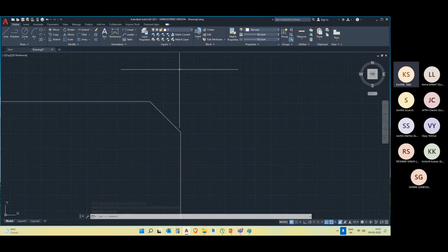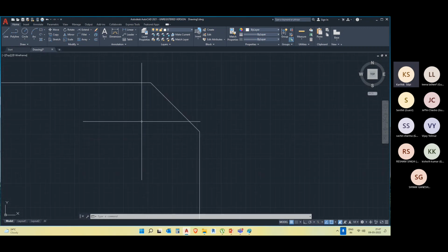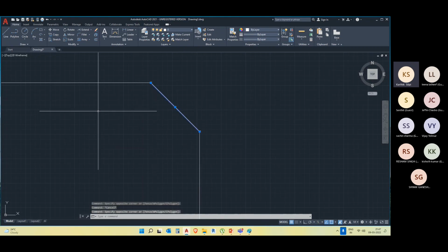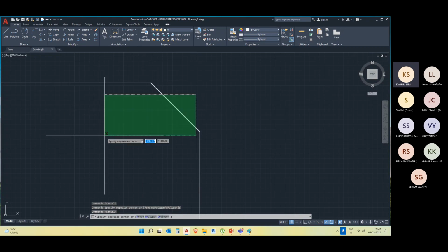So if you have a sharp edge, you may have human injuries or something like that, and it is also not aesthetically pleasing. Instead of that, they'll give a fillet wherever human interaction will be there, or wherever they want to avoid injury. But in some cases that is not required, or no human is going to enter there, or there is no possibility of human injuries. They'll just cut both ends. That is called a chamfer.